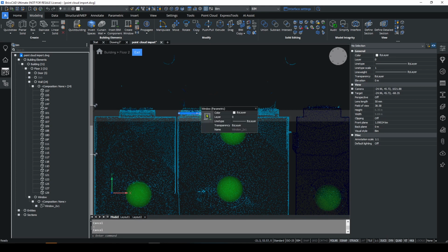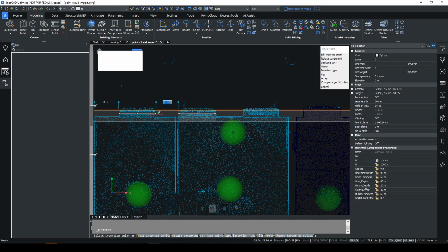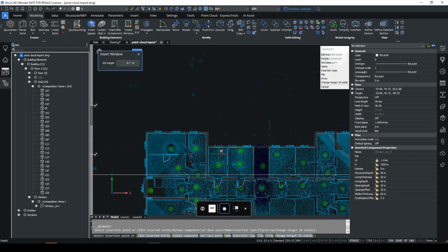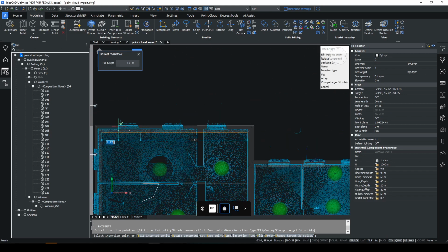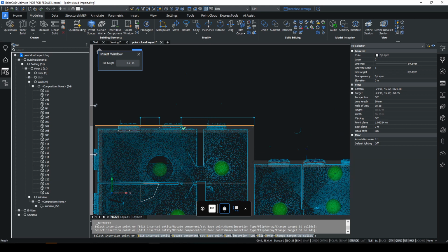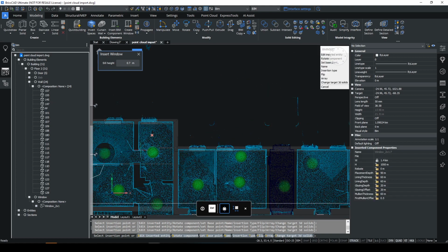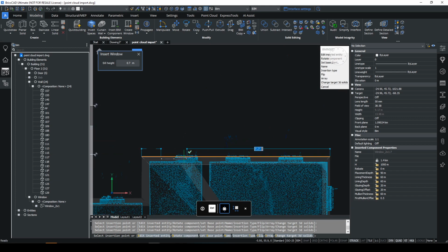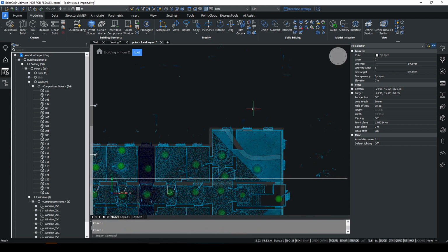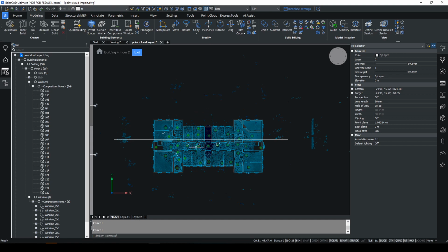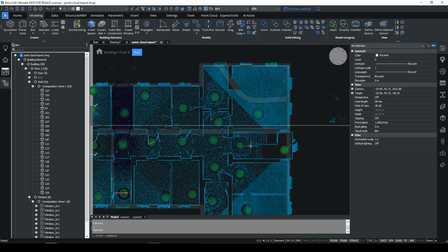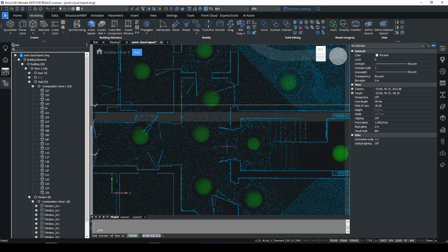And again, once you got it correct once, you will go and copy that, assuming you have multiple iterations of the same window type in your drawing. So we'll put a bunch of them on this northern face of the building, just so that when we do our dimensions in a while, we will have a few windows to document. So I'll put some over on this area as well. Okay, so this is a whole bunch of windows put in here. At this stage, we don't have automatic tools for columns, but if we did have some of those, you could easily use the box command just to draw one of these and give it a height here.